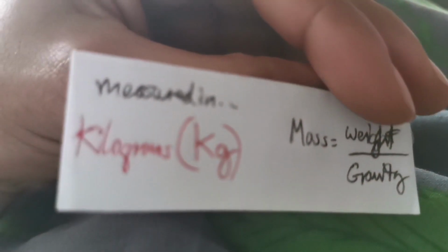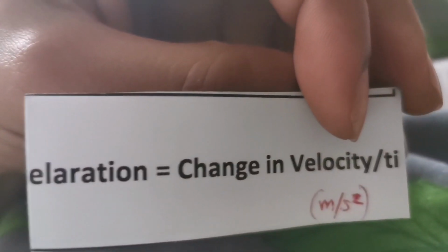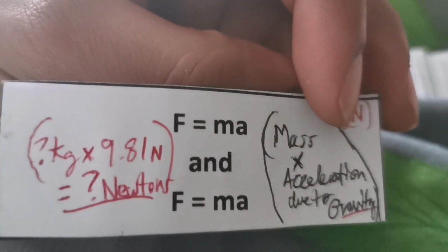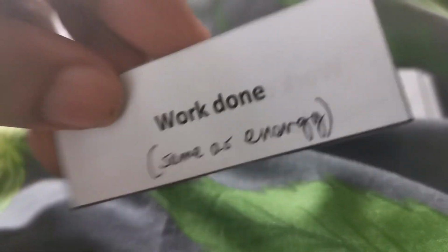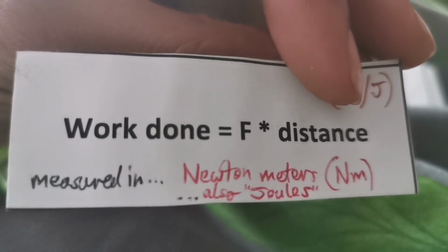We went on to work out the resistance of a conductor by using the formula resistance equals the resistivity multiplied by the length divided by the area. In other words, resistance equals rho L over A. Again, these video presentations are to put us in the position where we get the amount of knowledge required to go into the exam where a calculator wouldn't be used. Remembering the formula resistance is rho L over A is a good way of getting marks within this section.